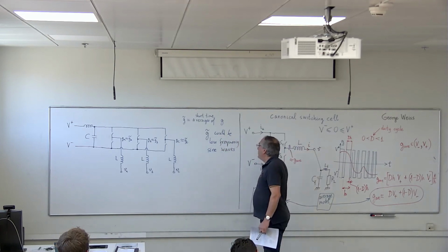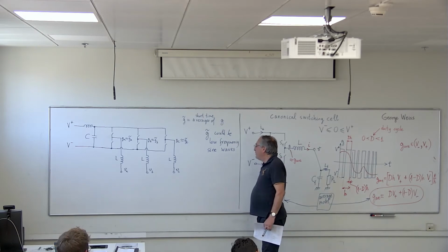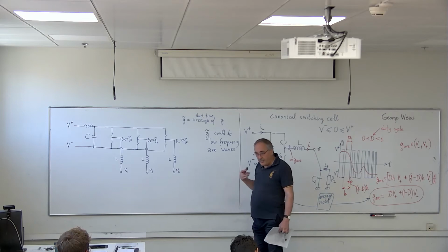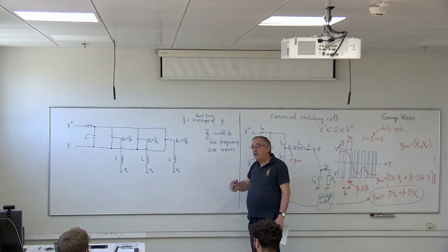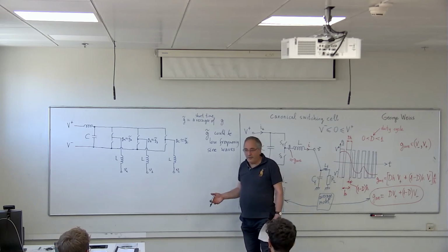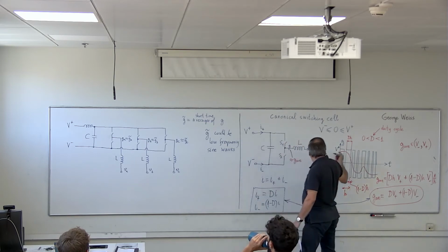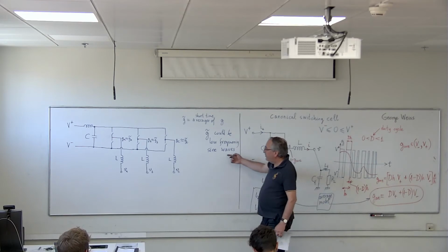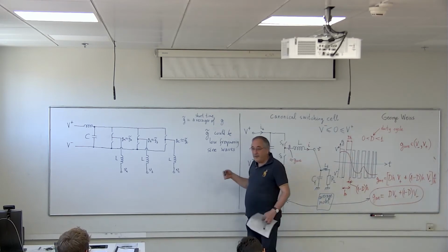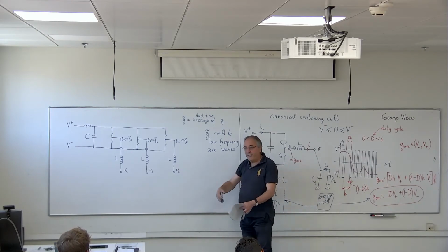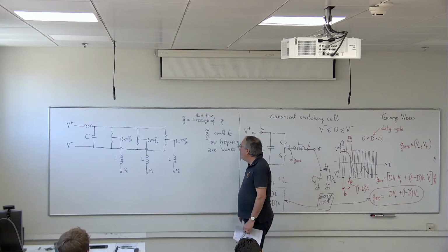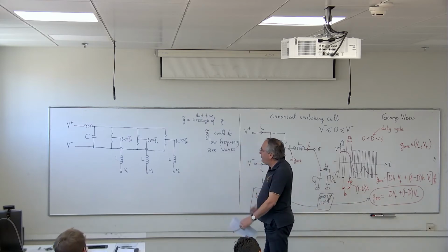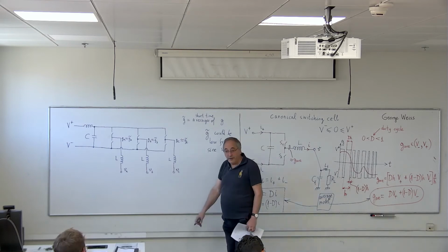What do I mean by low frequency? I mean low in comparison to the switching frequency. If the switching frequency, let's say, is 20 kilohertz, then if I generate here 50 hertz, that is very low compared to the switching frequency. Okay, so this is a most basic inverter.